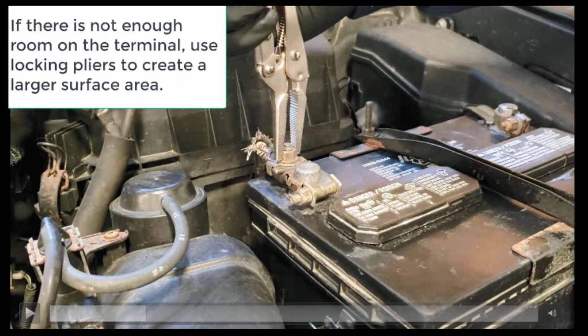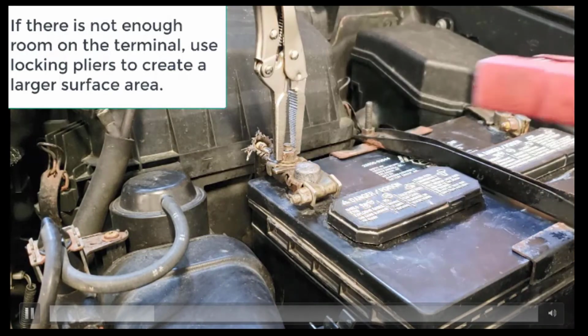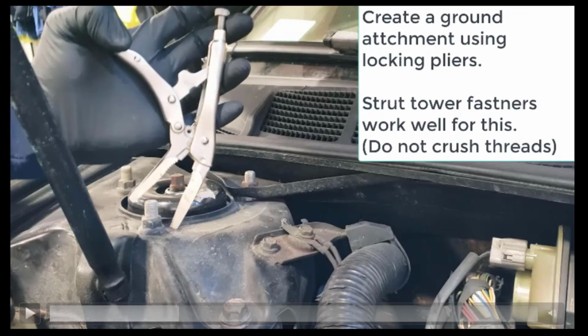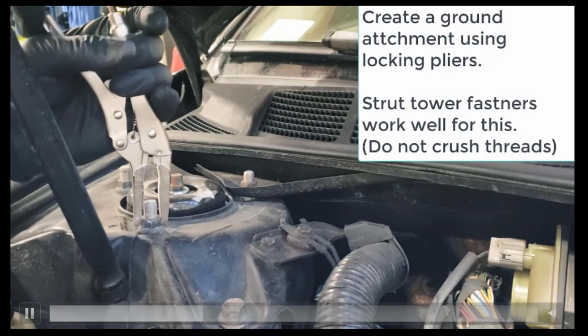If you don't have any room for a positive clip, you can actually use a vice grip or locking pliers to give you the surface area necessary to do the jump start. And this is by design. I actually put it sideways across the locking pliers to give me a better grip here. Attach that. Now, as you come in for the negative connection, notice I'm using locking pliers on a strut tower bolt. I'm using it on the actual bolt, not the threads. Be very careful not to crush the threads. This is a really good way to create a ground for yourself.